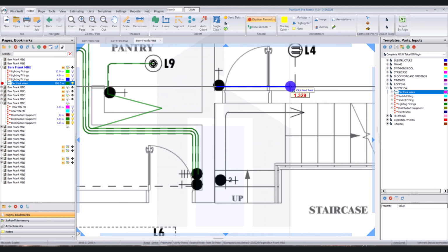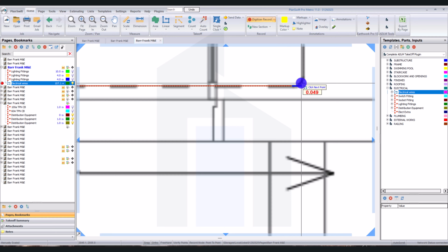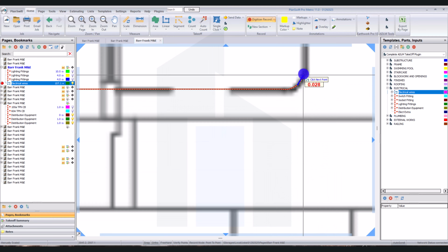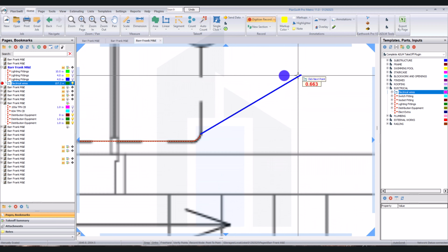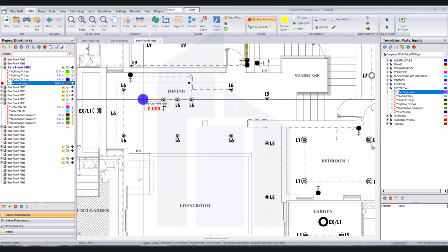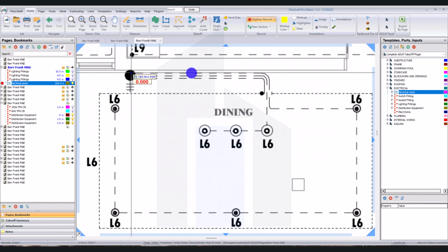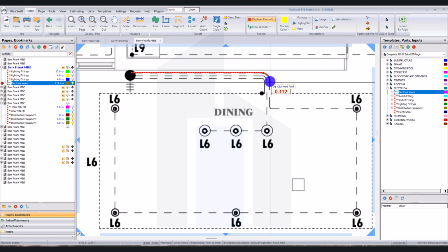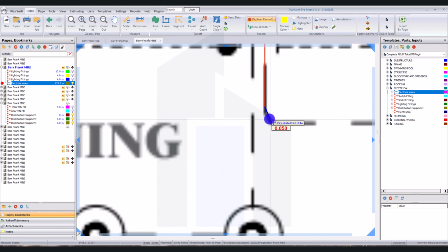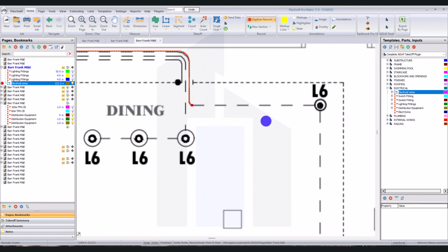So you can also do something like finding a route that leads back to the distribution board. So instead of having cable wasted on your takeoff, you can just create a route yourself and estimate that route back to the distribution board point. That also makes your work easier. I'm using A to arc. So let me just speed this up.